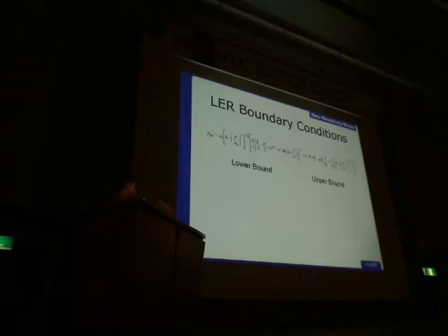So when you look at the final model, you still have the grain boundary reflectivity component, along with these sidewall specularity components. Those are still maintained there. Now let's talk about the boundary constraints, now that we have LER programmed into this. Let's talk about the lower bound. What happens when U is 0? When U is 0, you have a perfect conductor with straight sides, and mathematically it collapses down simply into the original equation you found.